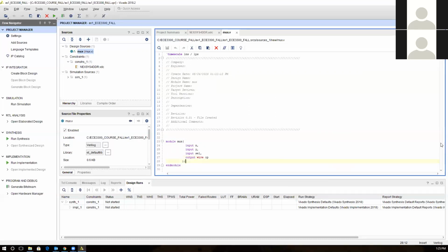In the beginning of the outline, I mentioned to you clearly that there are hardware modelings in Verilog. One is called structural modeling, one is called data flow, and one is called behavioral modeling. In behavioral modeling, you are describing the behavior of the circuit, which is like writing C. In structural, you are building with AND and OR, while in data flow, you are using the concurrent statement called assignment. So we can build our circuit using one of them.